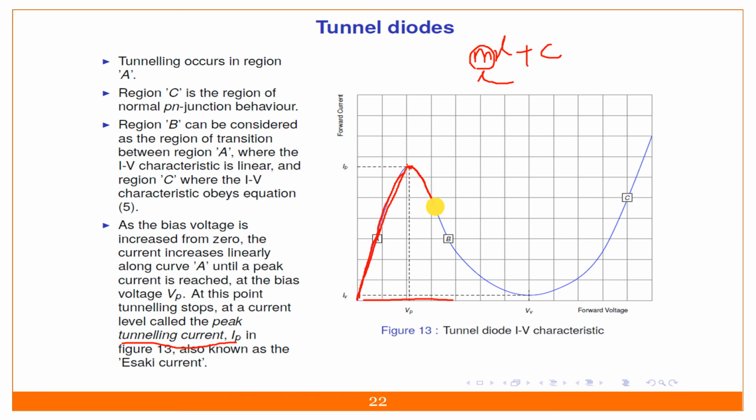The current is caused to decrease because in this tunnel diode, or in the Gunn diode, normally in the GaAs material, gallium arsenide material, we have two layers. That is the valence band, I will write valence band, and the conduction band. So what will happen if we are giving the voltage? In this GaAs, you will find three layers over here.